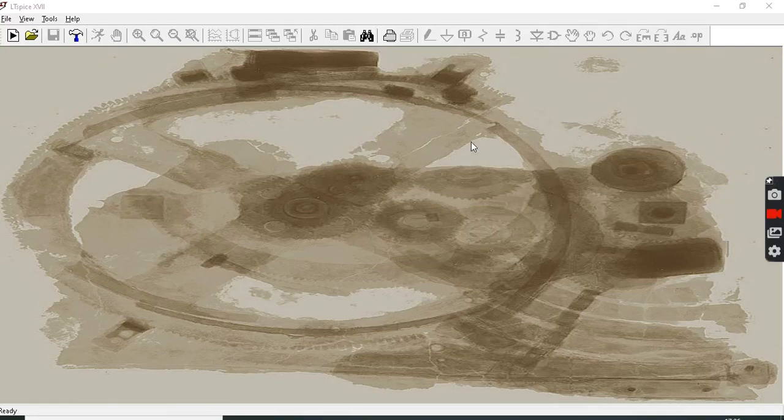Hi, this is a small tutorial covering transient analysis and AC analysis in LT-Spice. Earlier, what we have seen is DC operating point analysis. It calculates the DC voltage at each node and current for each branch in the steady state of an electronic circuit. Now, coming to transient analysis, it is used to analyze the changes in current and voltage over time when an input signal is applied to an electronic circuit.